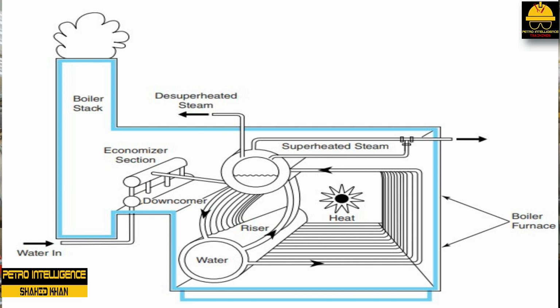exit the boiler. As heat is applied to the boiler firebox, water flows from the upper drum through downcomers into the lower drum. Tubes, called risers, cause water and steam to flow into the upper drum because of density differences. Boiler water circulation operates under the principle of differential density. When a fluid is heated, it expands and becomes less dense. Cooler water flows from the upper or steam drum through the downcomers to the mud drum, the lower drum, and then rises as some steam is generated.